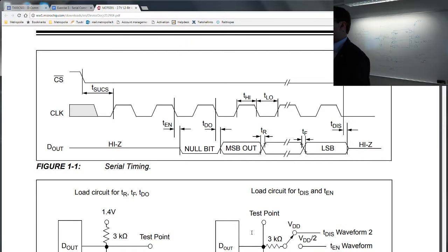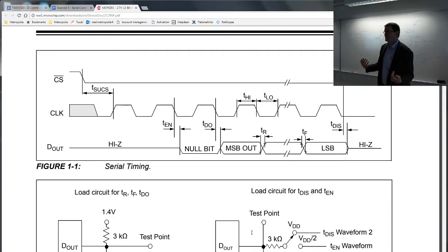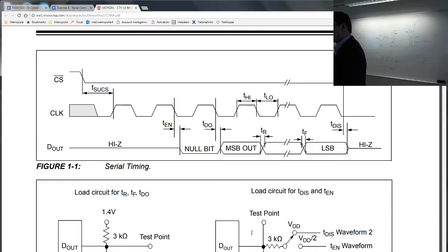Now the question is how to make this make any sense on your data value. Basically, this is the easy part. This is the lower byte. This is the higher byte, so that will be the highest nibble here. So what you need to do here is some bit shifting and bitwise operations with these variables. So basically, byte 1 should be shifted 1 bit right.